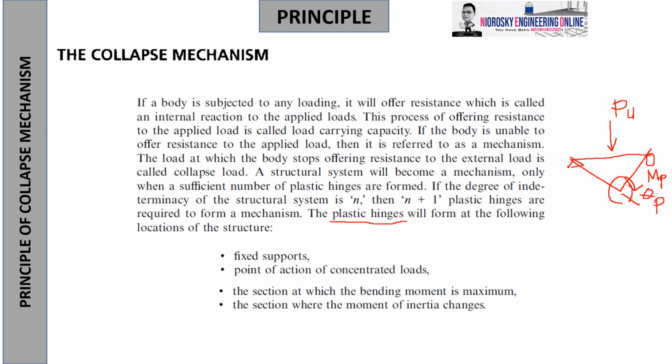Okay? And of course, in the support side, which is a hinge and a roller, may slope din of course, but that will be called a real hinge. Later, I'm going to emphasize this, but for the meantime, this is what we call the real hinge, or sa Tagalog, makatotohanang bisagra, if that's a literal term. But here for the theta P is the portion where we call it the plastic hinge, where there's not really a hinge, but for the purpose of deformation, there's what you call a fictitious hinge, or the technical term, plastic hinges.